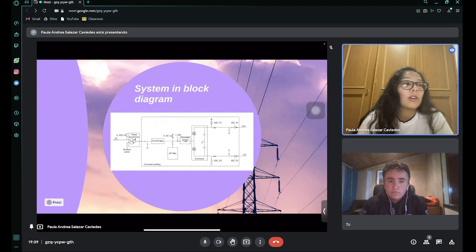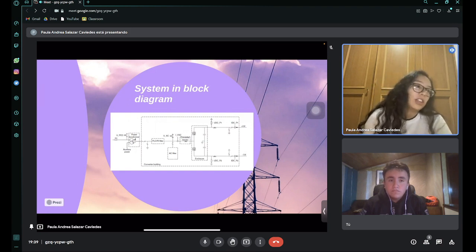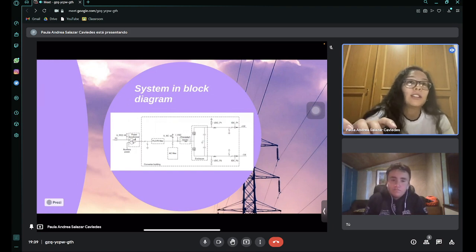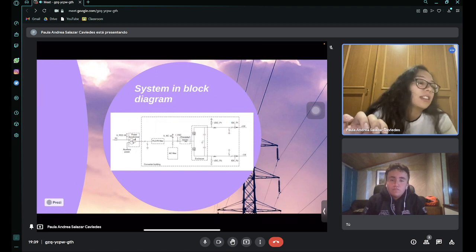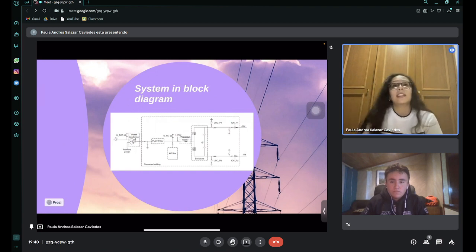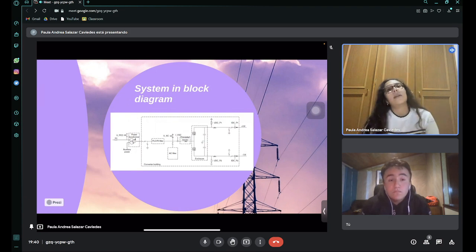In this system, we also use a lot of active and reactive power in the whole process, which gives energy to the system. Secondly, we have the converter reactors, in the middle of the image, connected in series to each phase. They compose the voltage source converter to permit continuous and independent control of active and reactive power.